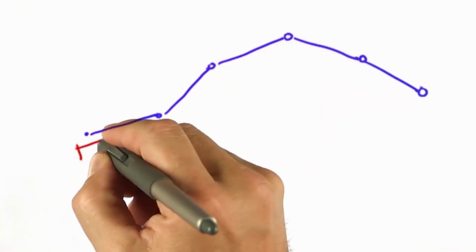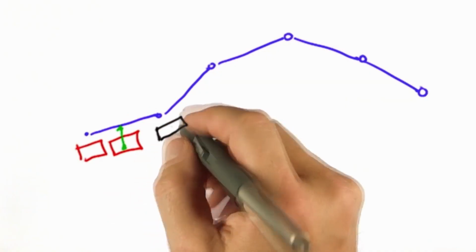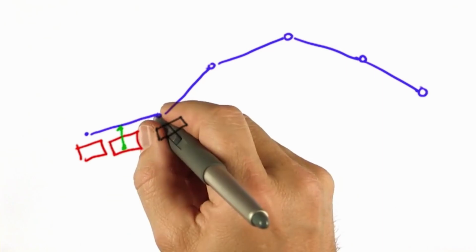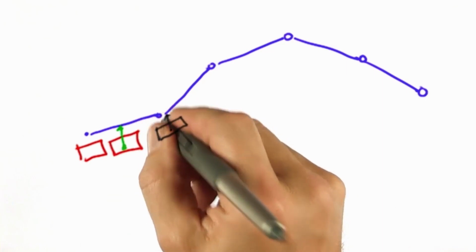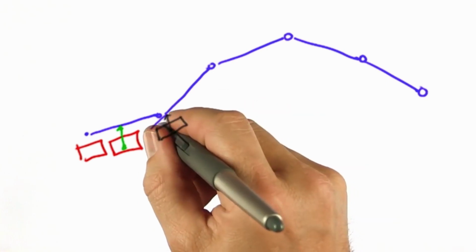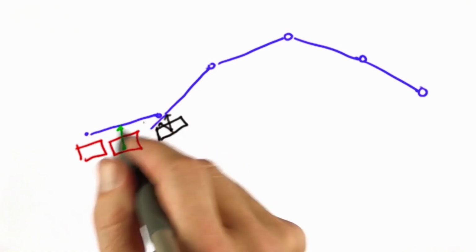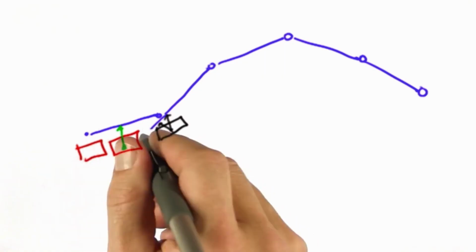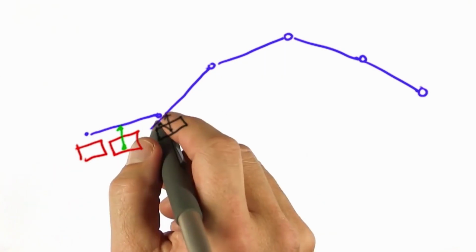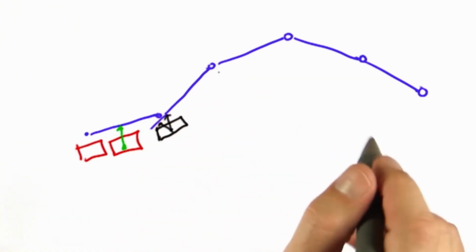When a robot drives along, it has a certain cross-track error. But as the robot state projects beyond the end of a line segment, as is happening here, we have to change the corresponding line segments to be the next one. So in addition to calculating the signed error relative to an arbitrary line segment, not just the y-axis, we also have to detect when the robot steps beyond the end of a line segment and switch over to the next one.